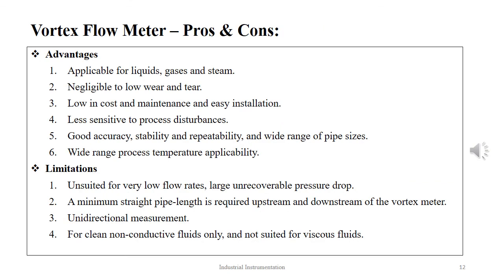The advantages of a vortex flow meter are: they are applicable for liquids, gases and steam. They have negligible wear and tear. They are low in cost and maintenance, and they are very easy to install. They are less sensitive to process disturbances, and therefore they offer good accuracy, stability, repeatability, and can cater to a wide range of pipe sizes. They have a wide range of temperature application.